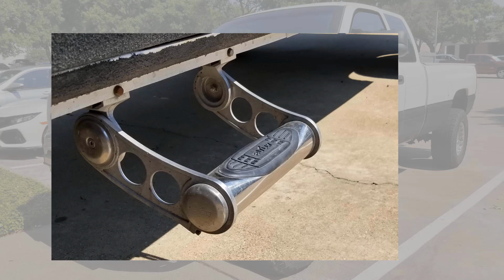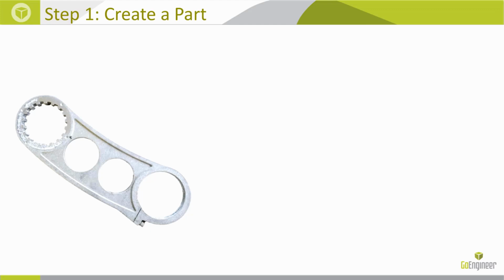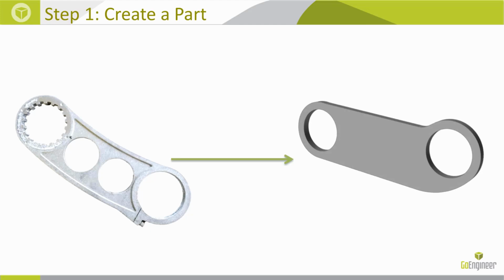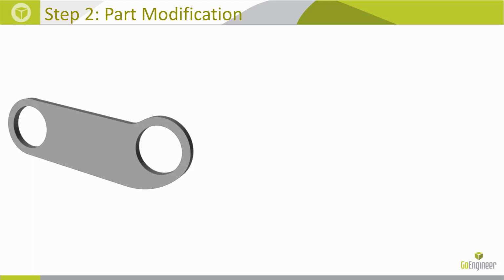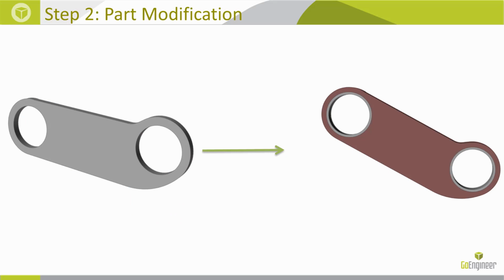So what we're going to do is we take that initial design, and I'm going to first create a SOLIDWORKS model out of it, right? Something relatively the same, because I'm looking at what is the best design that I can get. But I'm still in the initial conceptualization phase, so I'm not looking for something exact. And then we take that design and bring it into SolidThinking. I'm going to show you how I do this, but basically the first step is to create what's called my design space, the region that can be optimized and weight can be removed from.